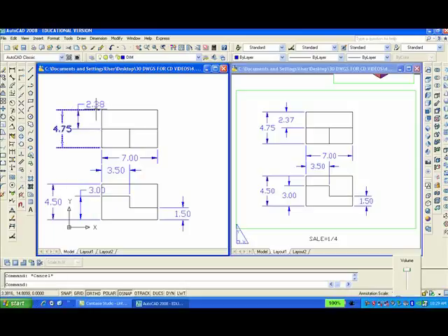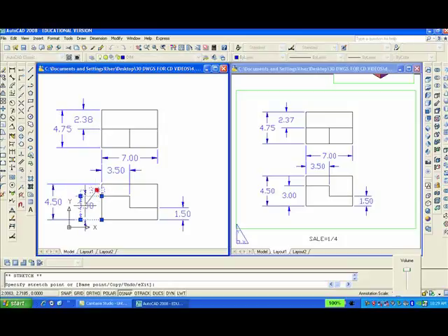These don't look too good, so I'm going to change them. I'm going to take off the object snap and the ortho. I'll click on that dimension, grab the grip and move it in here like this. Pick a point there. That looks better. And I can do the same with this one. With the grip, grab it and move it where I want to put it. Like there. Hit escape. Or I can even center it better since the O-snap is off. So that looks better.